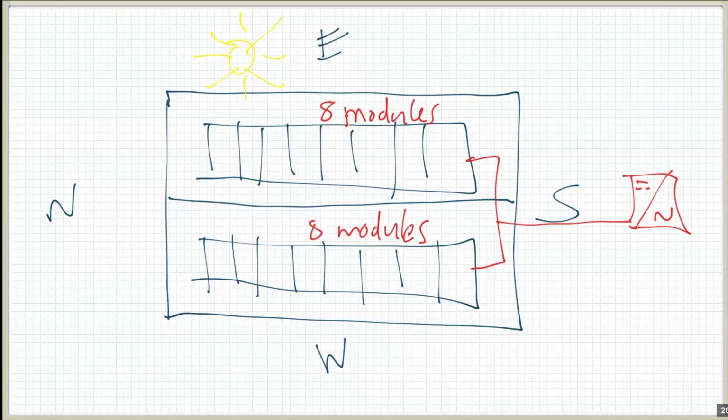Okay, I've got a question, Glenn, about the same different orientations on the same input. East-west seems fine, but what about northeast and southwest? Could I do that? Yeah, so I just generally draw it like east-west because it's a very obvious mismatch, but any mismatch will still exhibit the same temperature characteristics and irradiance characteristics on voltage. So it's the same as true of any mismatch array. You will still get a very similar voltage in both of those strings.